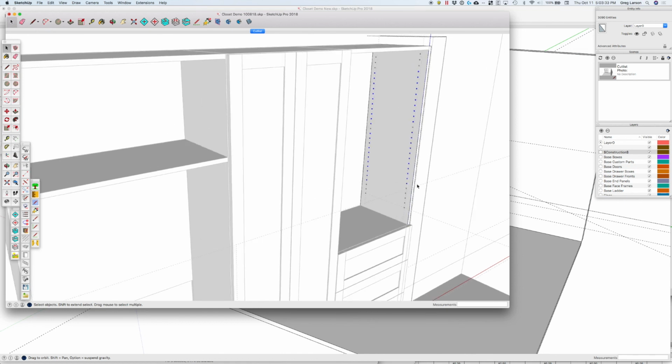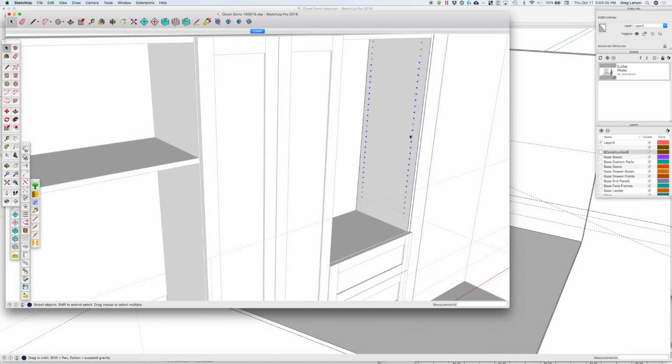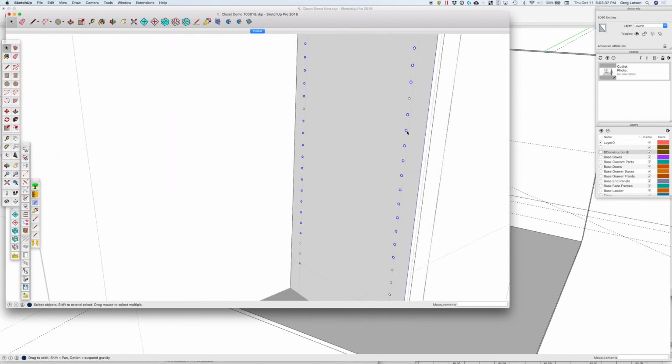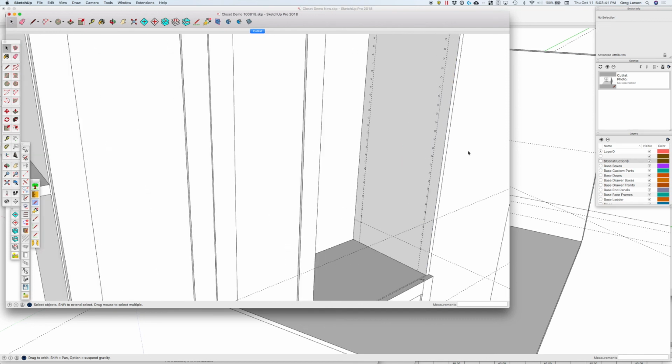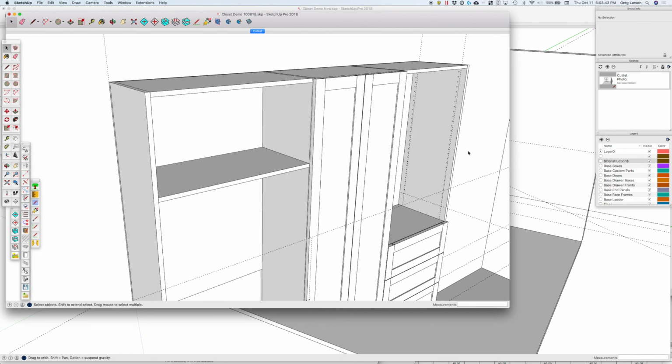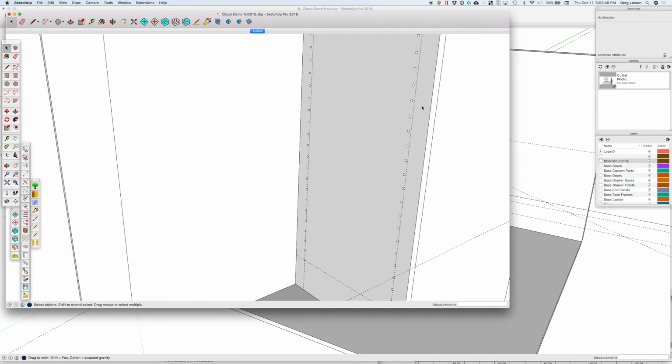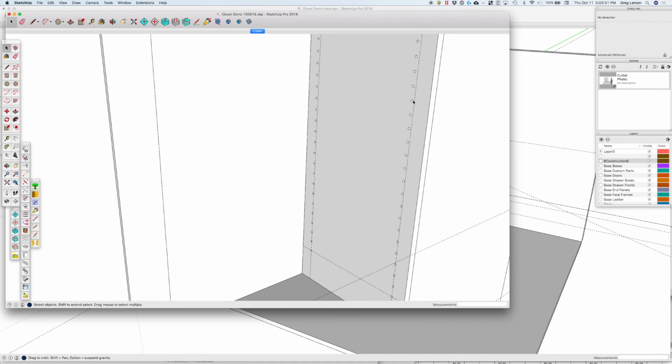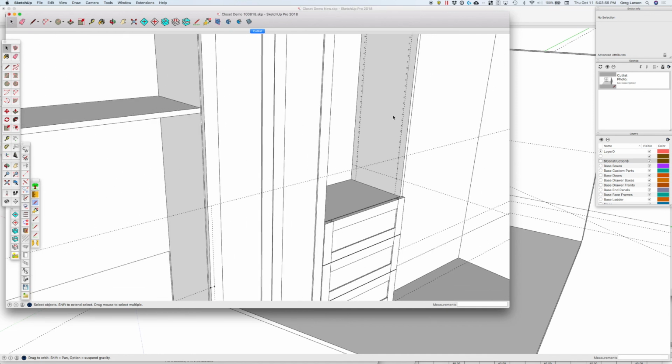Highlight some more by shift clicking until I got all of them, and then I could right click just those circles and say multiple circle push. So now I've got circles in there, and notice they're going off at an angle. That means when I did that move pulling them up, I wasn't on the axis moving up, I was drifting. So I would want to do that again.